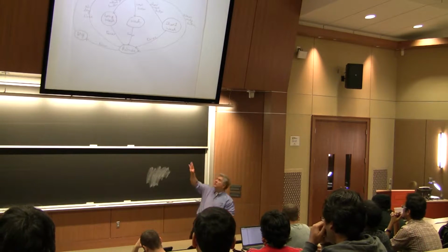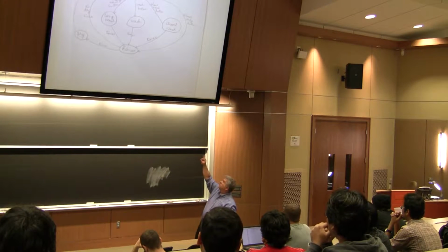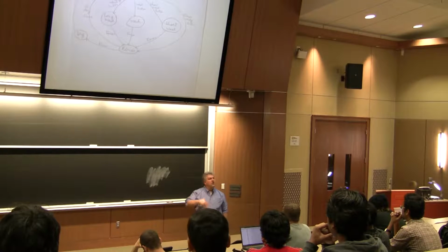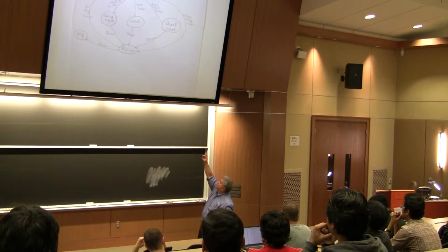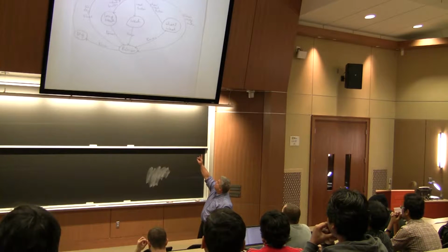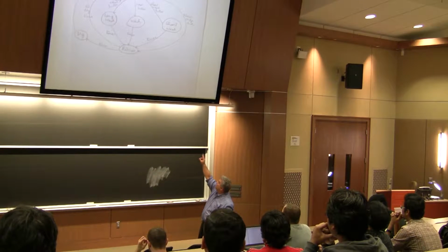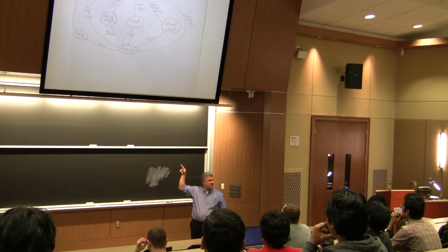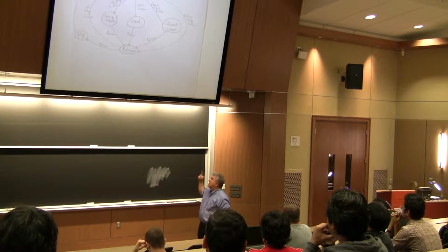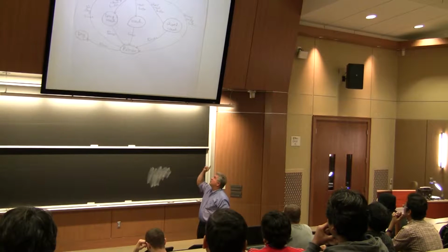Okay. Then it would check to see which button was actually pressed, and then start that specific state. But again, you're going to go from an initial state to a new state, whether it be long wash, short wash, or rinse. And then after that, depending on what the input is, it will either go to the dry state or it will go back to idle.